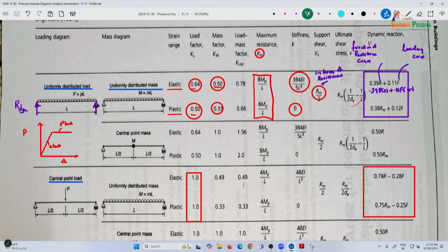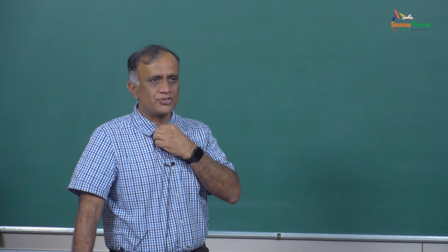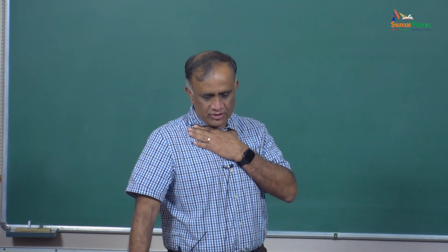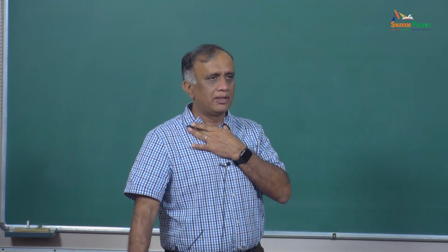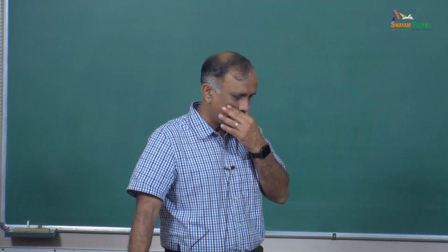So, one thing you could think of is, should you do both an elastic analysis and a plastic analysis? You can take the average stiffness equal to KL elastic plus KL plastic, averaged. As an engineer, you have a lot of leeway to work with different assumptions, and a reasonable assumption to do just one analysis is to consider the stiffness as the average of the two. Is it accurate? No. But does it work for design purposes? Perhaps.